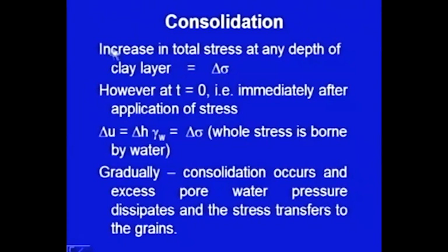So, the increase in total stress at any depth of this clay layer will be delta sigma. This is the total increase. Just in the beginning, theoretically at time t is equal to 0, immediately after the application of the stress, the excess pore water pressure will be equal to the total stress which has been applied at the top.